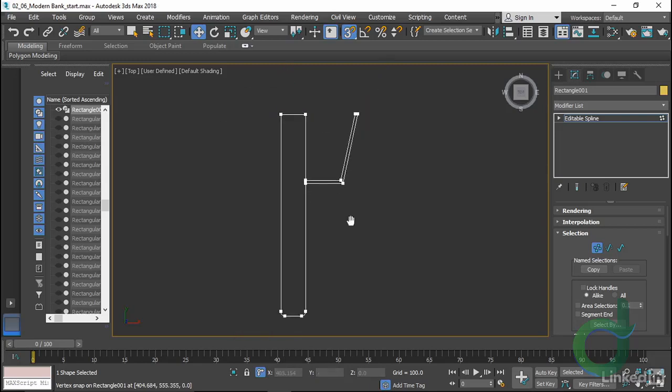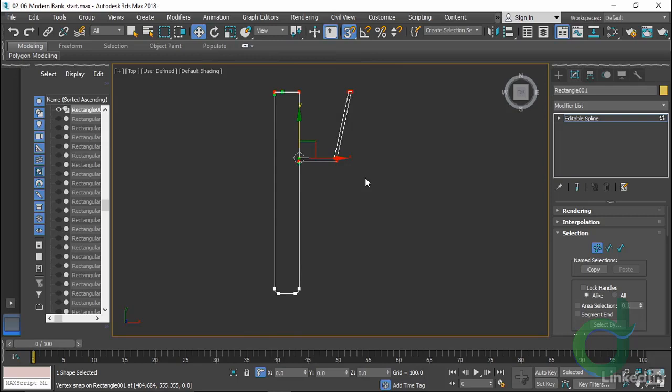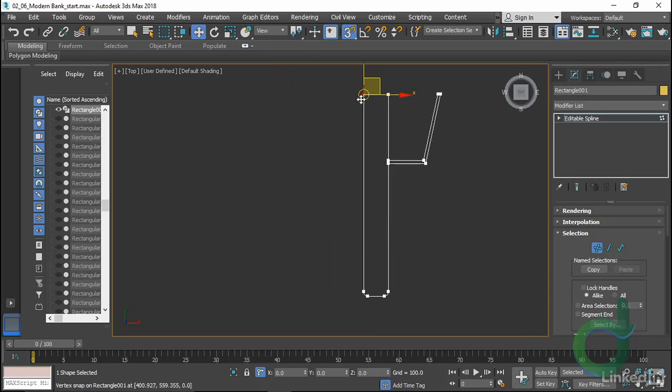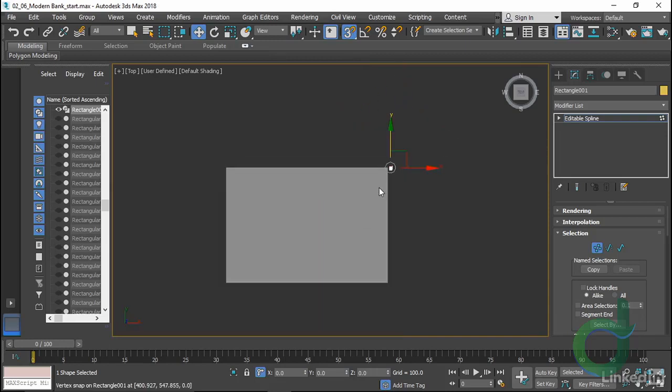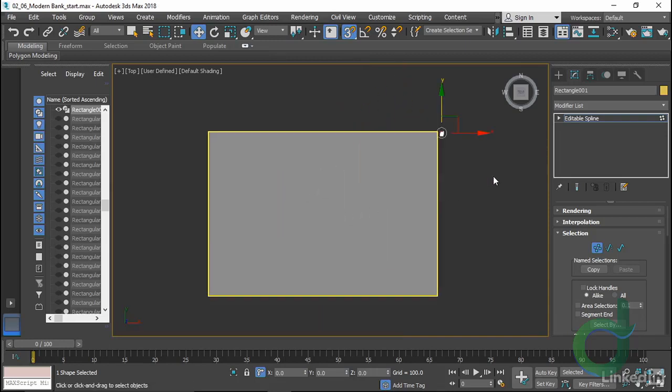And lastly, take all these vertices and right-click and make them corners. Then I'll set this one, right-clicking, as the first. That means that when it goes on a path, it'll run through that vertex. Now I'll take this roof and add in that profile.